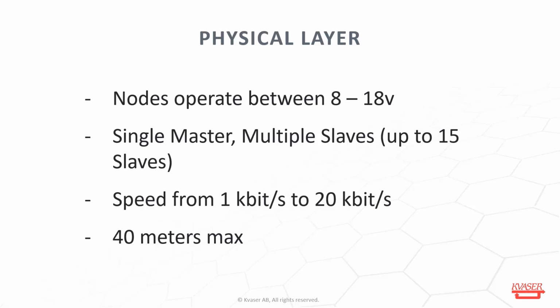So let's say you have a smaller system that works the turn signal. Just something simple like a turn signal. One node will say if it's turning right, one node will say if it's turning left. It'll communicate what's going on in that LIN cluster up to the CAN bus so that a larger computer system can tell what's going on, possibly do something from there. That's just some of the possibilities that you have with LIN.